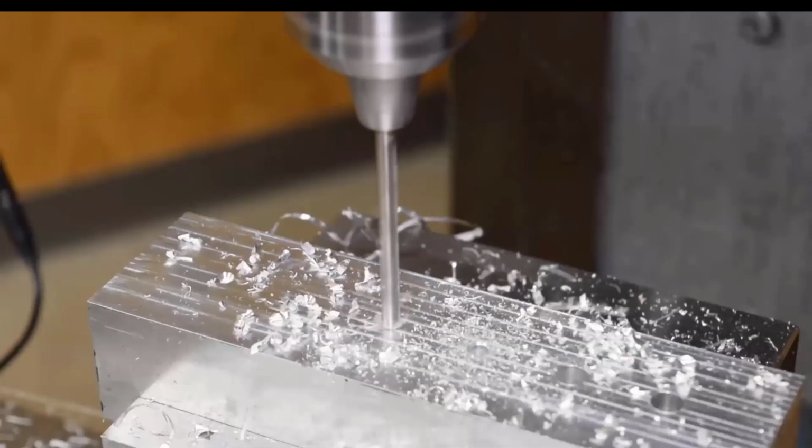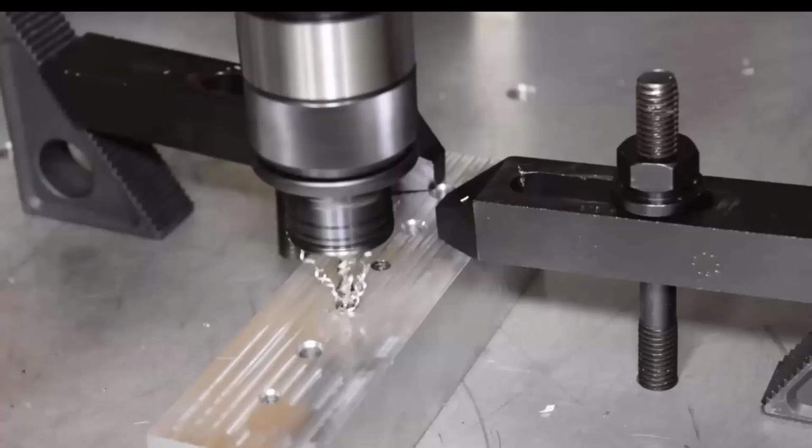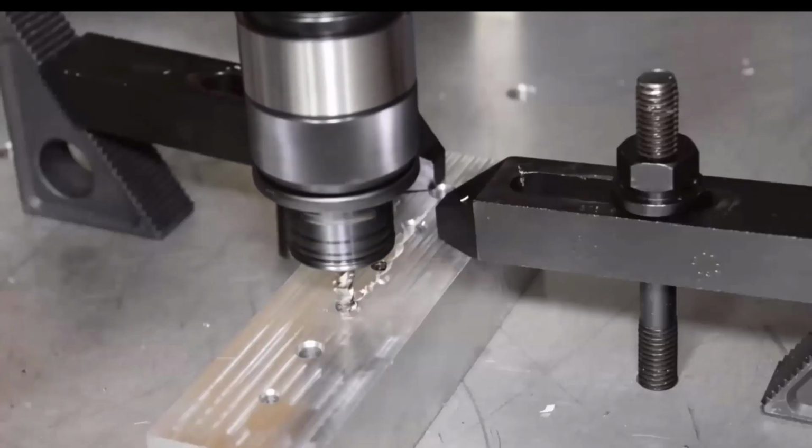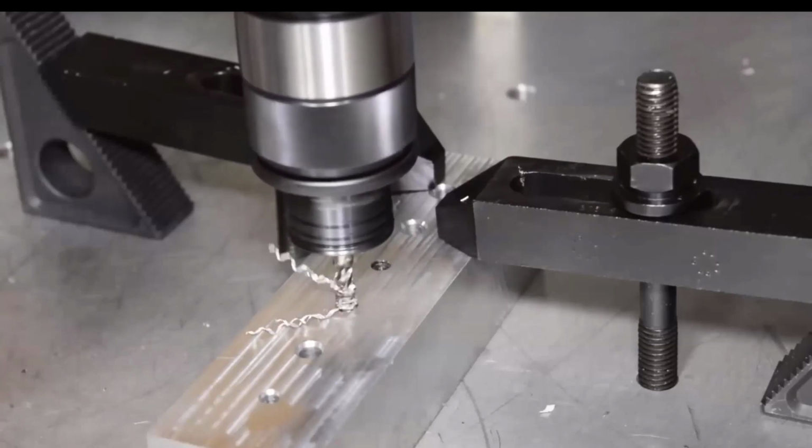When designing tapped holes, you need to have enough thread engagement to allow the bolt to be fully tightened to its tensile limit. For threads in most metals, a thread engagement length of around 2 times the nominal size of the screw is sufficient. An interesting nuance of threaded holes is that they don't share the tensile load evenly along their length. In this FEA, we're simulating tightening a steel screw into an aluminum tapped hole, and you can see that the first few threads do almost all the work. Once you get beyond about the 8th thread, there is almost no load being carried. Hence, there is little benefit to additional thread engagement, and it simply adds to the assembly time.